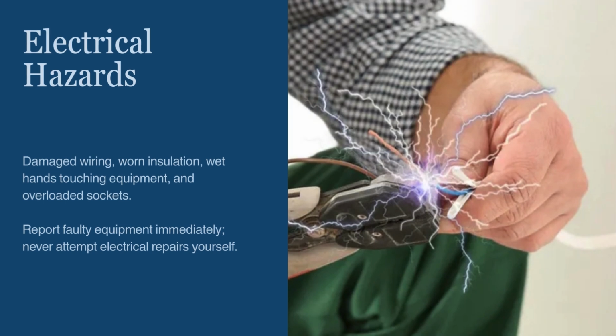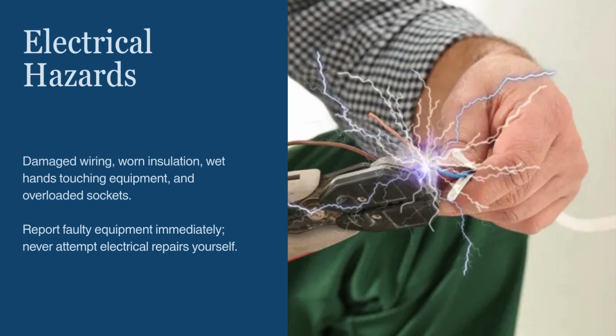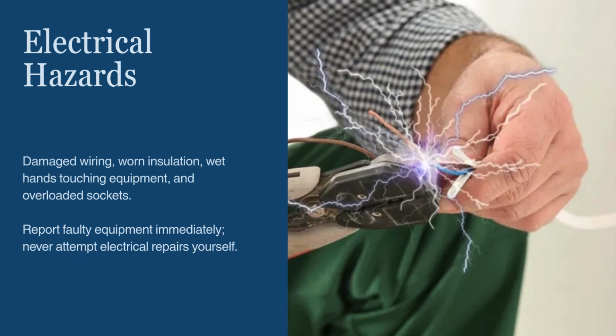Next are electrical hazards. These occur when electrical equipment is faulty, damaged, or used incorrectly. Real-life examples include exposed wires, damaged power cables, loose plugs, or overloaded extension leads. Electrical hazards can cause electric shock, burns, or even fires. Always inspect electrical equipment before use and report any faults immediately. Never use electrical tools with wet hands or near water.